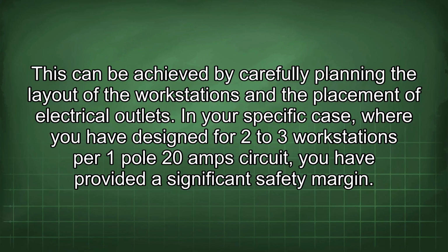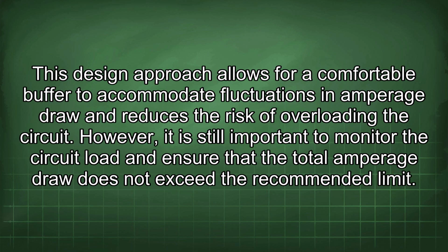In your specific case, where you have designed for 2 to 3 workstations per 1-pole 20 amp circuit, you have provided a significant safety margin. This design approach allows for a comfortable buffer to accommodate fluctuations in amperage draw and reduces the risk of overloading the circuit. However, it is still important to monitor the circuit load and ensure that the total amperage draw does not exceed the recommended limit.